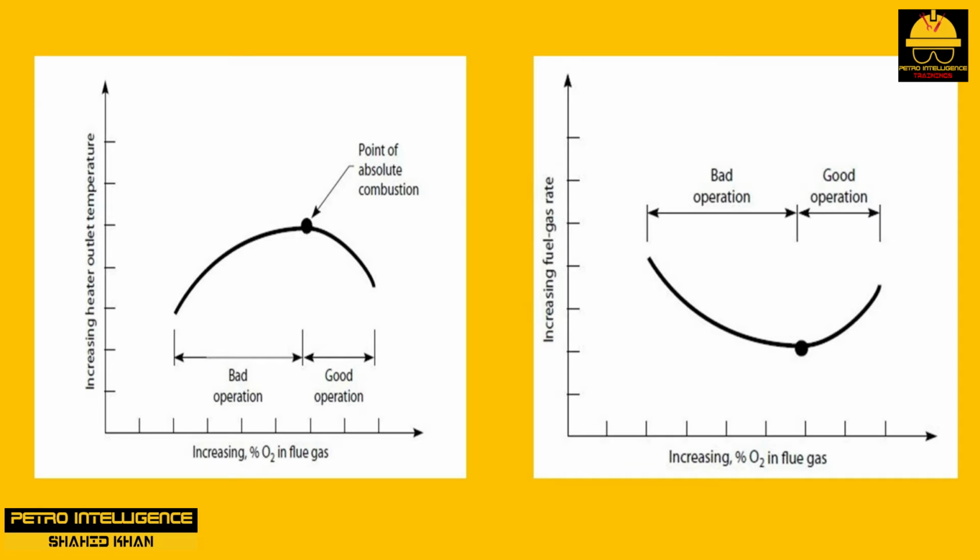One week I was switching the blowers when I forgot to shut one of the 2 down before starting up the 3rd blower. I then had all 3 blowers running at once. Our normal heater outlet temperature target is 680 degrees Fahrenheit, but while I had all 3 blowers on, the outlet temperature rose rapidly to 740 degrees Fahrenheit. Rather than cutting the fuel gas back to reach a 680 degrees Fahrenheit outlet temperature, increasing excess oxygen, he shut down the 3rd blower and dropped the furnace temperature back to 680 degrees Fahrenheit but also continued to run fuel-rich, without enough air.